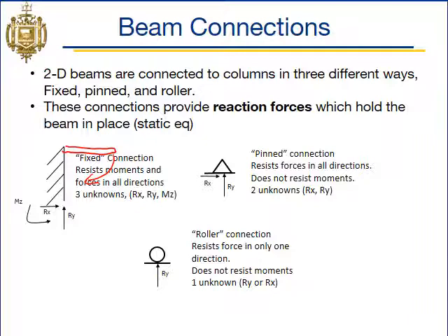So next we have the pinned connection. So our pin connection resists forces in all directions, but does not resist the moment, right? So we resist an x and a y force, but not a moment. So if we had a beam that's sticking up like this, right? If we put that beam like that, it could very easily rotate that way or that way, but it wouldn't be able to move left or right. So over here in the fixed, it can't rotate, but on the pinned, it can.